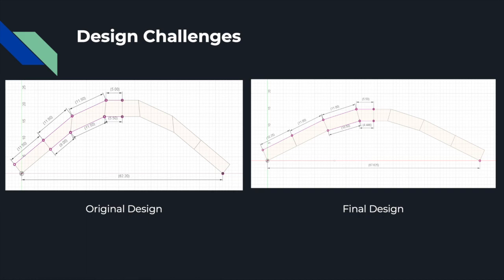In theory, this original design was great except for the flaw that became evident the more we considered how forces were being transferred along the arch. Because in our original design, we had our central piece, which is a trapezoid, long base side down, we realized that none of the other pieces were positioned underneath it to help carry the load of the bridge effectively. Plus, this design would overstress the latches between the sections sooner, as they would already be trying to cope with varying components of force along the arch.